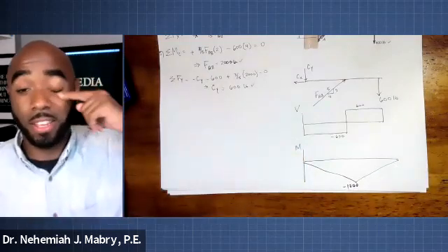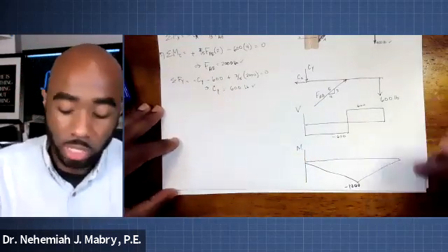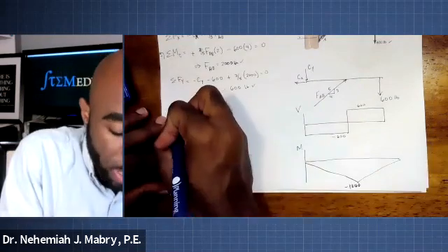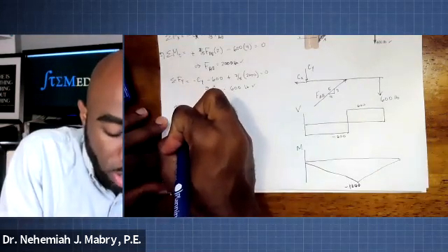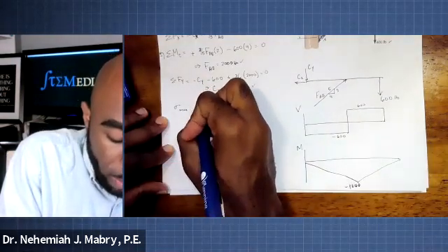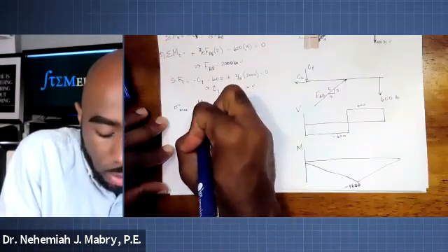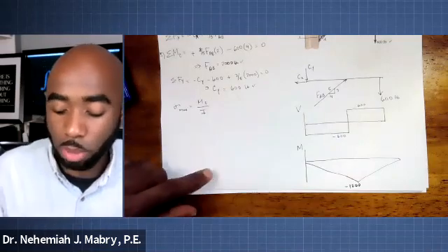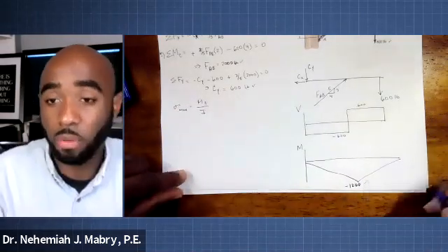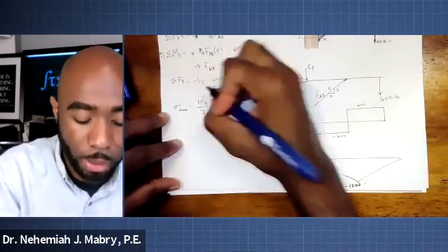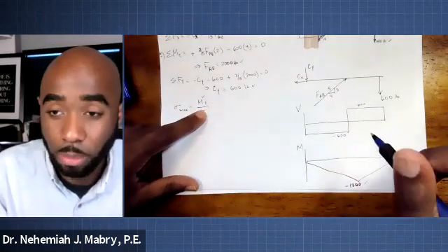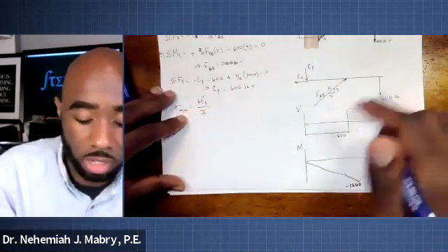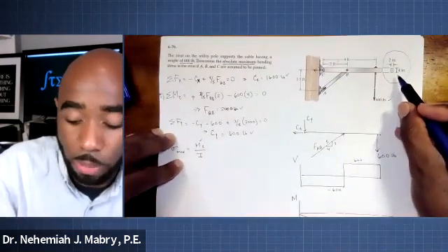All right. Now, we need to know our maximum bending stress. Here's the equation. I told you at the beginning, I gave you a spoiler alert. It all comes around this right here. What is going to be the maximum moment? Well, we have it right here on our diagram. So we got that. Boom. What is C? The maximum distance from the centroid. We already saw up here. I told you to come back to that.